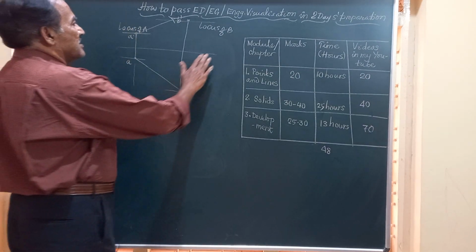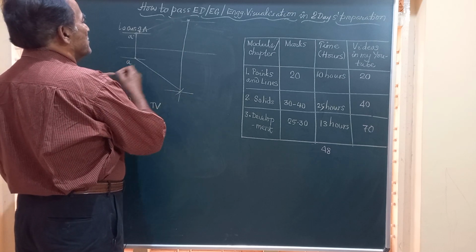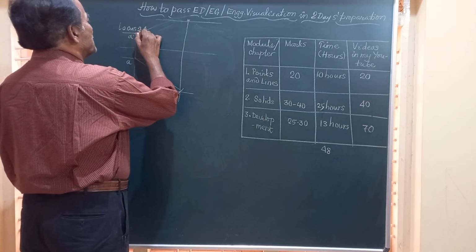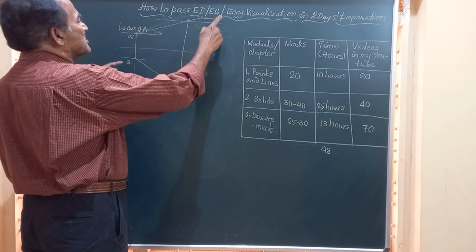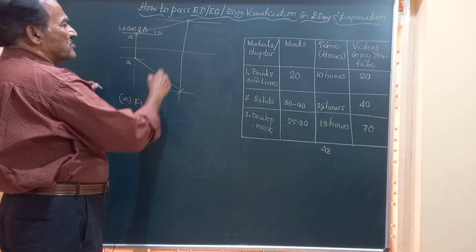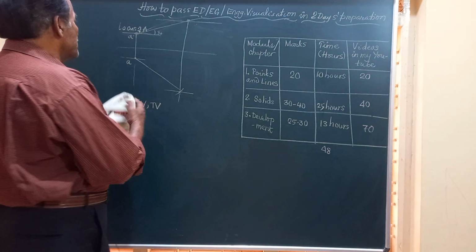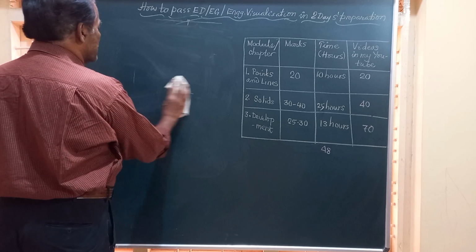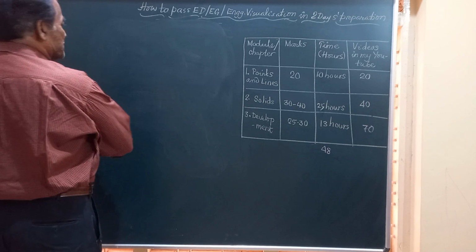and VP, etc. Similarly, friends, in the same problem, they can also give you the angle made by the line with the HP. Suppose theta is given to you, some angle, 30 degrees. So once this is given, you will be able to find out the true length of the line and the angle. Like this, friends, varieties of problems can be solved using this particular data, wherein the end projections, that is to say, the positions of A and B, are both given to us.